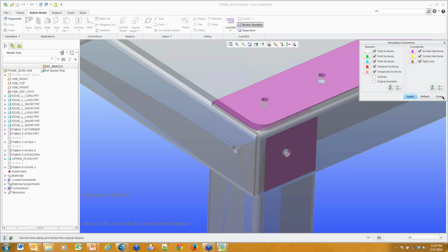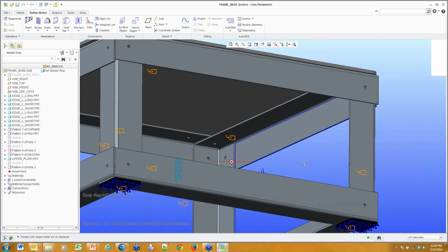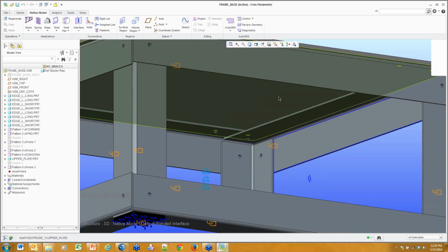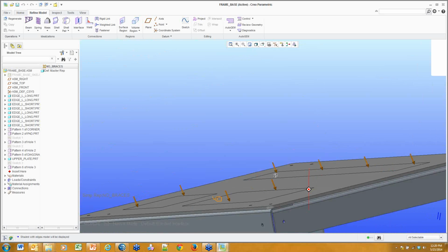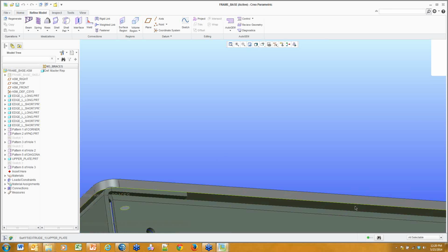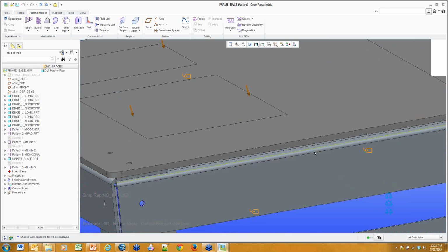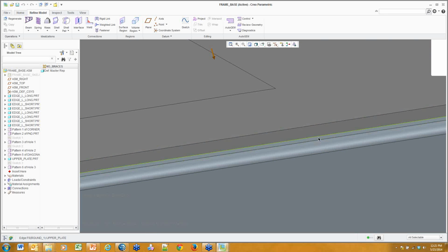Okay, that is accurate. Now, we do want to put a bolt in, and we'll get to that shortly, but there is one additional interface called a contact interface. Contact simply means, okay, it may be a little bit difficult to see, but we have this top plate right here. Contact means if you put a contact interface between the bottom side of this plate and the top side of this piece of angle iron right here, they are not currently touching, but under a load, it is possible that contact could occur.